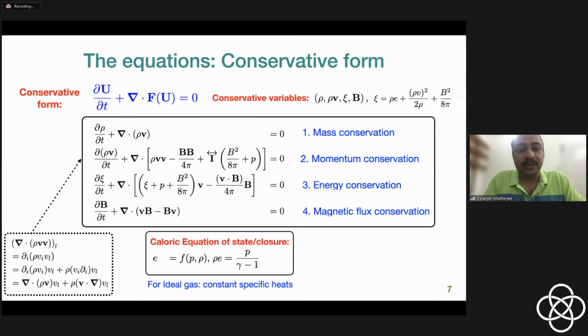And since now you're writing the equations in a form that is given in a conservative form, as you can see, you do not need to evaluate any of the divergences, any of the derivatives. So if you write the equation in this form, del u del t plus divergence of this, all you need to do is then integrate this over the surface. The divergence goes away because of Gauss's theorem. And all you need to do is evaluate the fluxes at the surfaces. So your scheme becomes an integral scheme compared to a differential scheme.